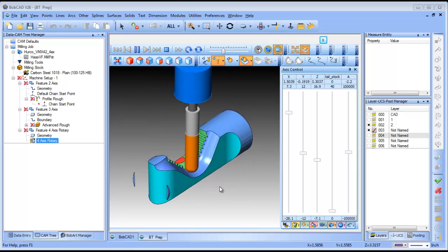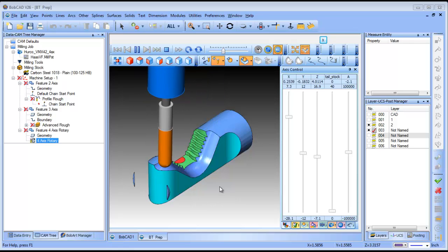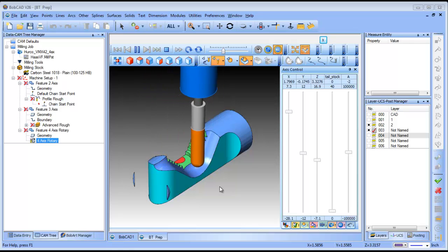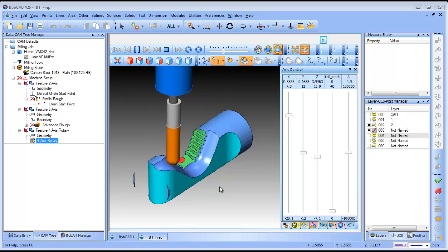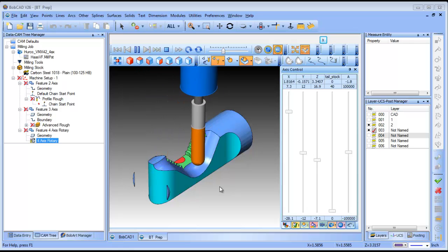I don't know, when I ran the rotary I was like, you know what, if I run it down the length it doesn't look that bad. Initially I was running it back and forth, but you can see just with a little bit of workflow process, you know, profile, rough, 3D toolpath or rotary in one orientation, now we can rotate the part to the next orientation and pick up with the additional strategies.